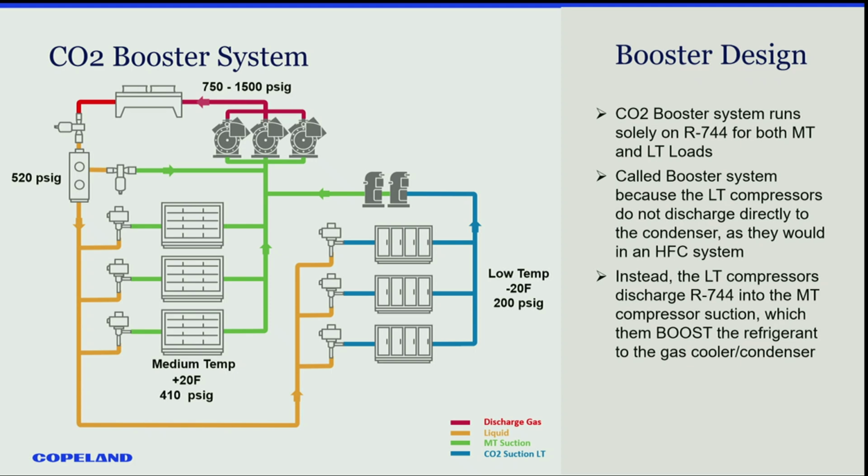There's talk about what we need to do to get it higher. On industrial systems already, everything blue, yellow, and green is 90 bar in a lot of industrial jobs. 90 bar, 1,305 pounds. And the supermarket industry is thinking about what we need to do collectively to go from 650 pounds on my liquid and suctions to maybe higher so we don't have release events.